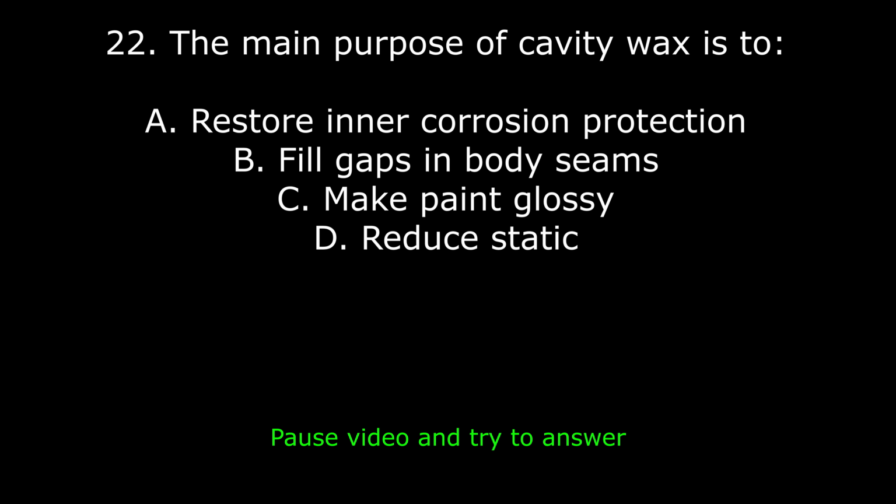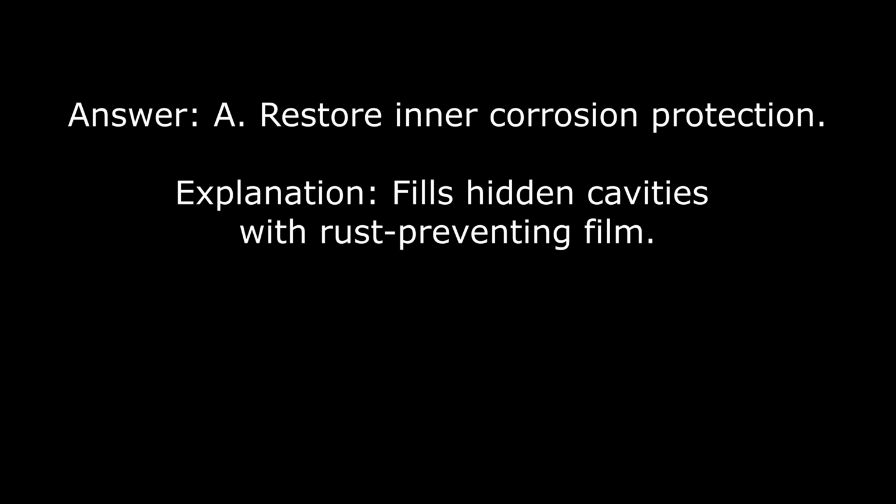22. The main purpose of cavity wax is to A. Restore inner corrosion protection. B. Fill gaps in body seams. C. Make paint glossy. D. Reduce static. Answer: A. Restore inner corrosion protection. Explanation: fills hidden cavities with rust-preventing film.